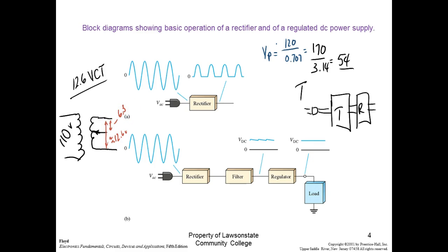This is exactly what's on your house. Y'all understand that? So on your house, if you come around off the 2 outsides, you get what we call 240. If you come off between the center and the side, you get what we call 120. Now that's just what NEC calls it, but it's going to be a range inside there. Plus minus 10%, I believe, is what Alabama Power allows.